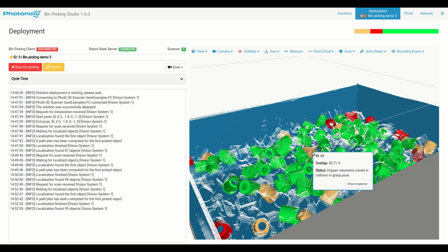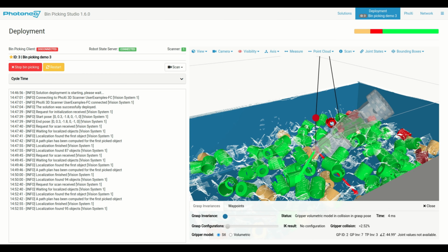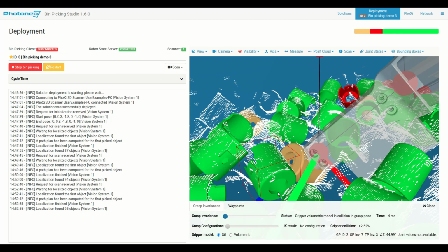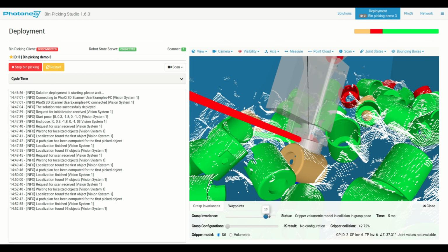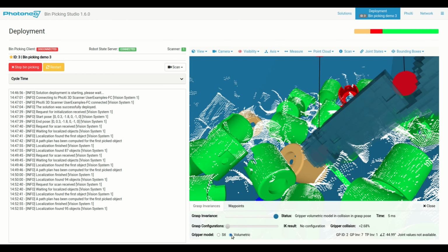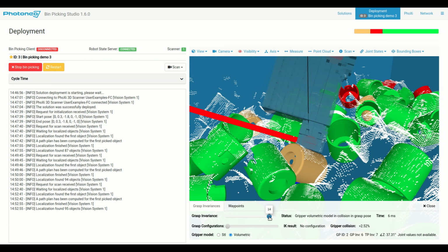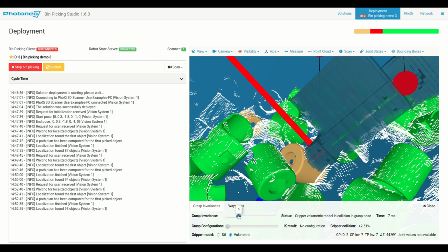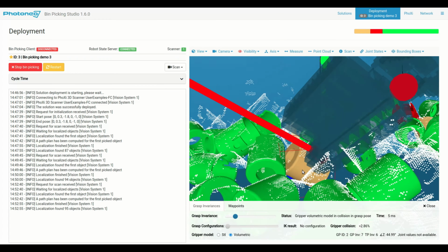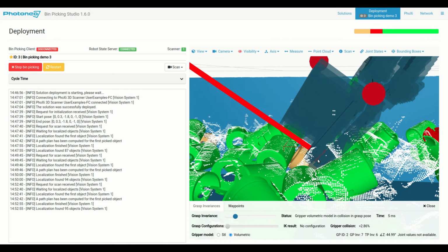You will want to use the volumetric representation while previewing the grasping waypoint when it failed to be computed because the amount of gripper in collision exceeds the allowed value. It is in fact the volumetric model that is used for collision checking during the grasping of the object. This enables more accurate visual inspection.